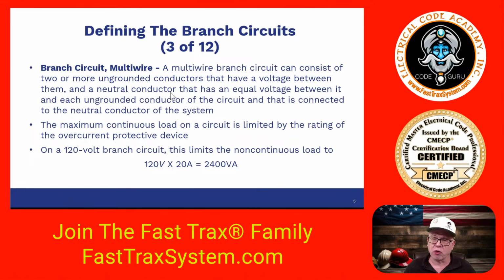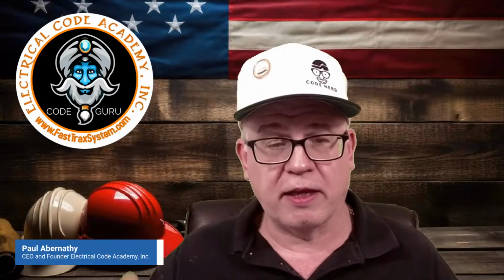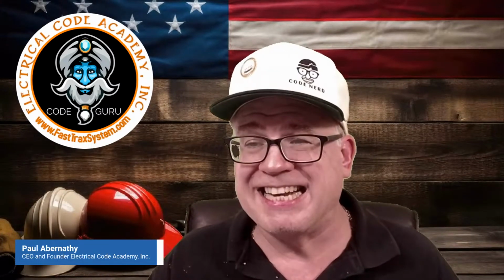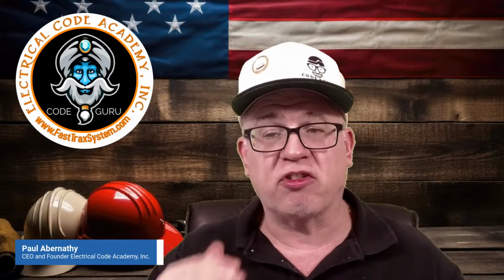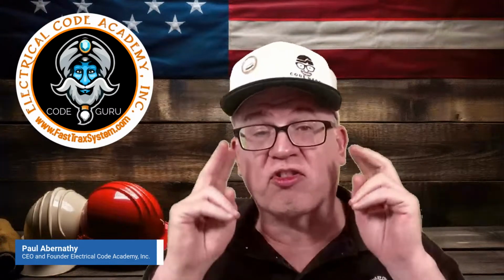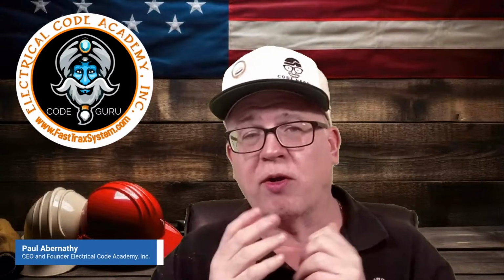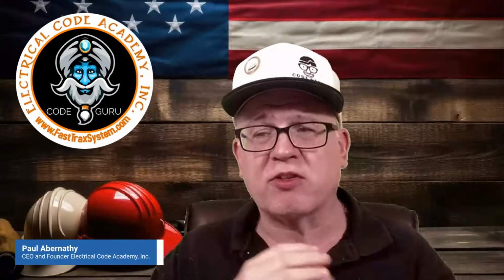And it says it has a neutral conductor that has an equal voltage between it and each ungrounded conductor of the circuit, and that is connected to the neutral conductor in the system. Okay, so I have a system, let's say it is a 14-3 with a shared neutral, and I'm using it on an identified breaker with identified handle ties, so that ensures they're on different phases or different legs in the panel. So I've got 2 separate circuits, but it would be a multi-wire branch circuit. So like a 14-3 or 12-3 where you're sharing that neutral, this is a typical 120/240 volt setup.